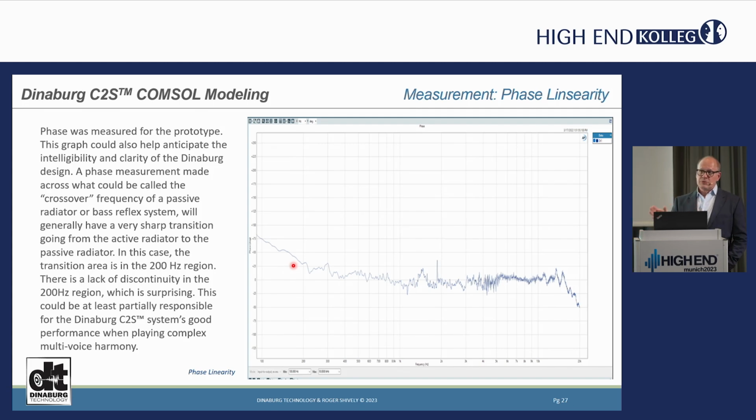and we could listen to both the passive radiator with the traditional design versus the passive ring radiator, and compare the two, listening on axis and off axis. You could hear the same thing that was heard when you listened to this device on axis and off axis: there was a greater clarity in the vocals as you went off axis with this type of alignment versus one that had a traditional passive radiator. And that is one of the things that we were seeing, that the off-axis response was stable and had less distortion as well.